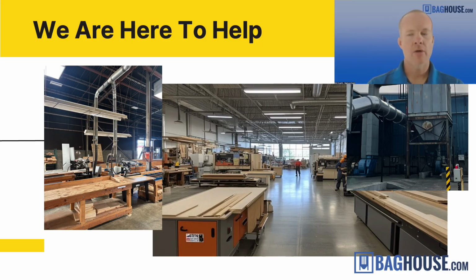The challenges of these types of projects usually have to do with getting information upfront from our customer. So if we know exactly how many machines, where they're located, what the pickup connection point sizes are, and where the dust collector will be, we're 90% of the way there. We can design a dust collection system based on that. But if we only get bits and pieces of info and we're kind of flying blind, that's where typically the design process takes a bit longer. There's potential changes and so forth. The layout changes, things like that. We find out, oh, actually, we're going to add a few pickups right here. All that impacts our design process.